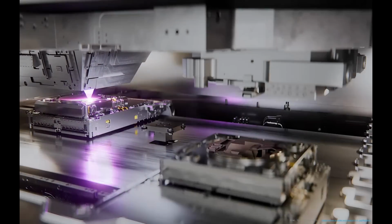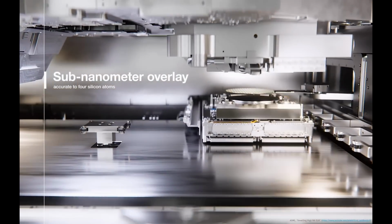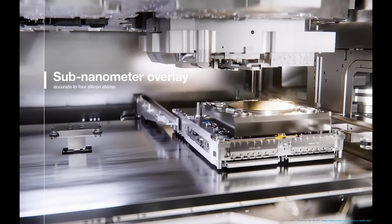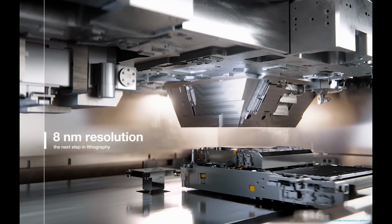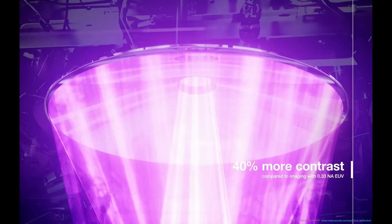And then you hit the wafer stages. You have a metrology stage first, so now a new wafer gets inserted and gets measured with this laser, and they claim they can align everything to 4 silicon atoms. Right? While this thing is accelerating at 32G.